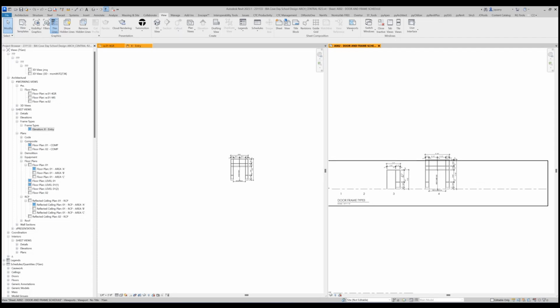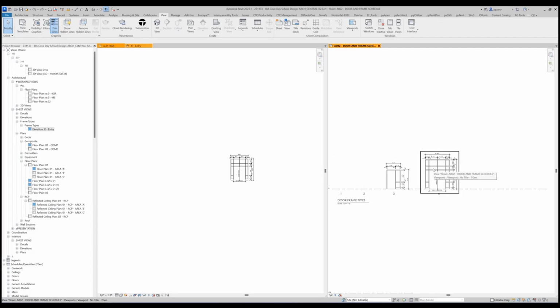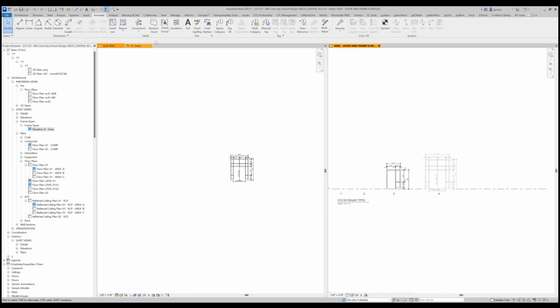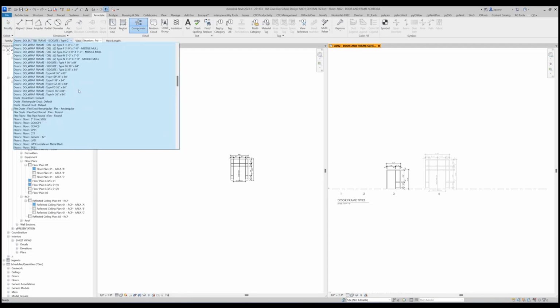I can't do a legend component of a curtain wall system, unfortunately. Right, right. It'd be really awesome if I could. And it's been a while since I checked, so maybe I should check this real quick. Does it do curtain walls, curtain panels, but it doesn't do the mullions. Yeah, because those are system families that are nested. Nested system families are what curtain walls are.